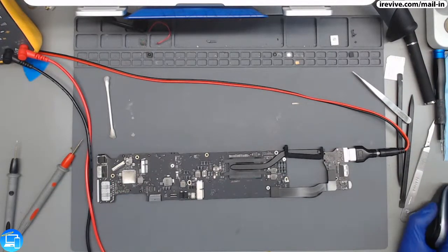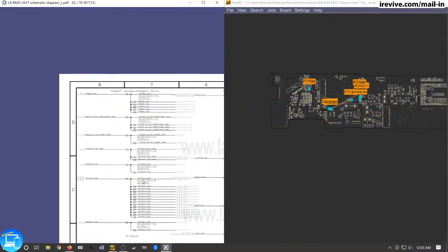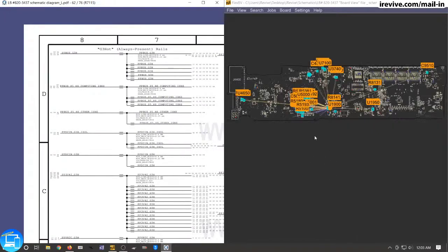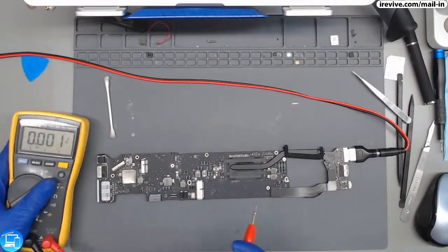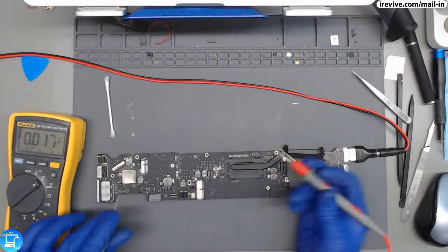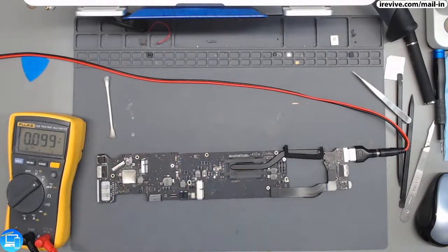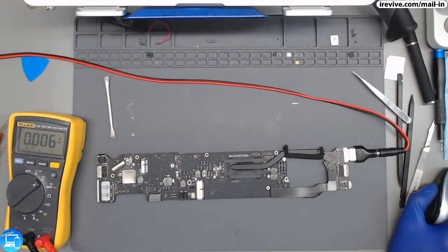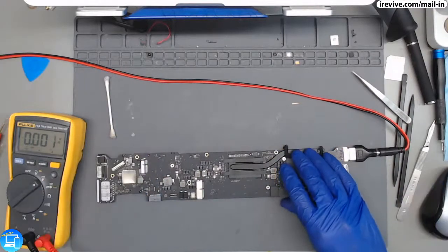Okay, back onto our, that's right, I shifted things here in my OBS, so things are a little off. Let's check out to see if we have PP3V42 G3 hot. And that's usually around this part of the board. Present. Okay. Do we have real-time clock? Let's flip it over and check that out.